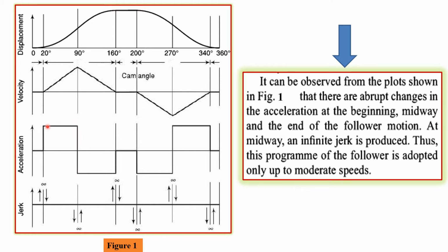Earlier it was getting accelerated, now it is getting decelerated. Then again it becomes zero because this is the dwell period, there is no velocity imparted, so there has to be no acceleration here. Again, during this return period, this is shown by a negative sign of the acceleration. So this is basically the uniform acceleration. Then it changes the sign and it becomes a uniform retardation now.